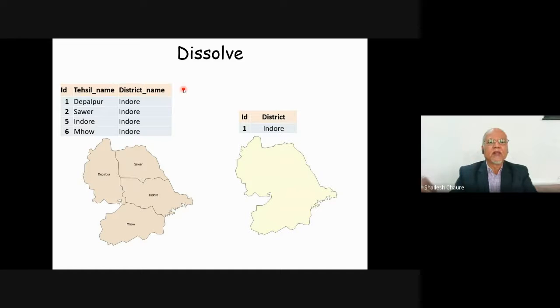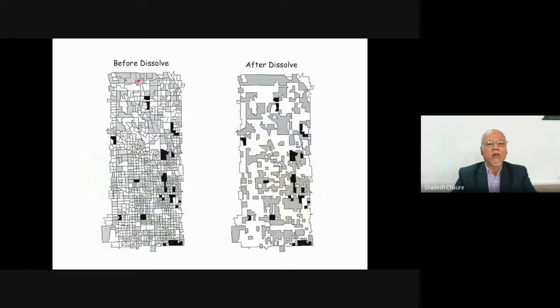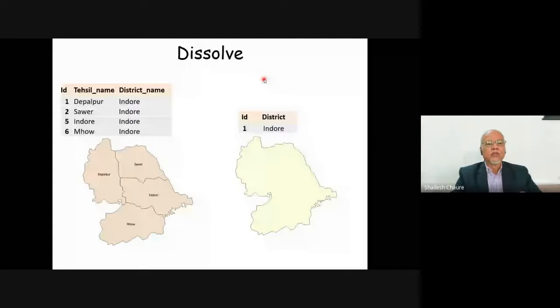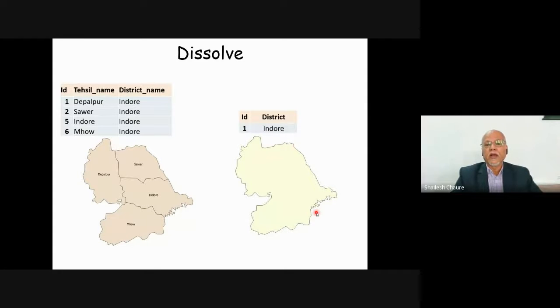Or, as I gave another example, you put some value like AAA or 111100. Using that field also you can dissolve, like how it was dissolved here. Because all these polygons have the same gray color, it means they have one common attribute. So using that common attribute, the dissolve operation will just remove the internal boundaries, and it will retain only the outer boundary. Okay. So this same thing we'll use here on our data so that we will have a distinct boundary like this. So this dissolve operation will work, and within no time you will very accurately create an outer boundary. That is something wonderful.